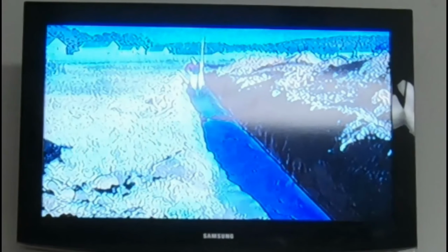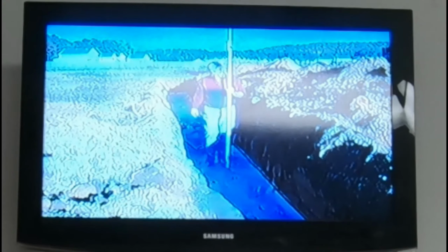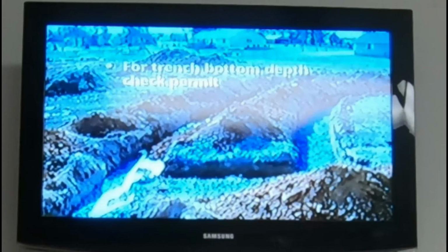An aggregate or gravel system must be installed in accordance with the following minimum design and construction criteria. The aggregate itself shall be 1/2 to 2 inches in diameter and pre-washed. Absorption lines and trench bottoms shall be true to grade, that is, level for their entire length. Trench bottom depth shall be based on what is indicated on the permit.